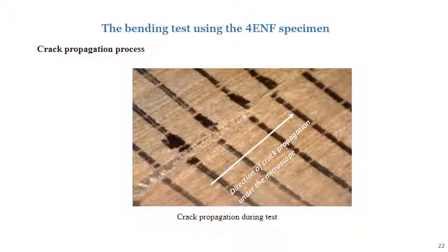To measure the length of the crack during propagation, a scale was marked on one of the edges of the sample as shown in the figure. However, we realized that errors can be made when identifying the bottom of the crack. In the figure, a discontinuity can be observed from the first black vertical reference line, detail 1. However, the position of the crack tip could not be defined, as it cannot be guaranteed that the discontinuities on the black lines correspond to a continuity of crack propagation.